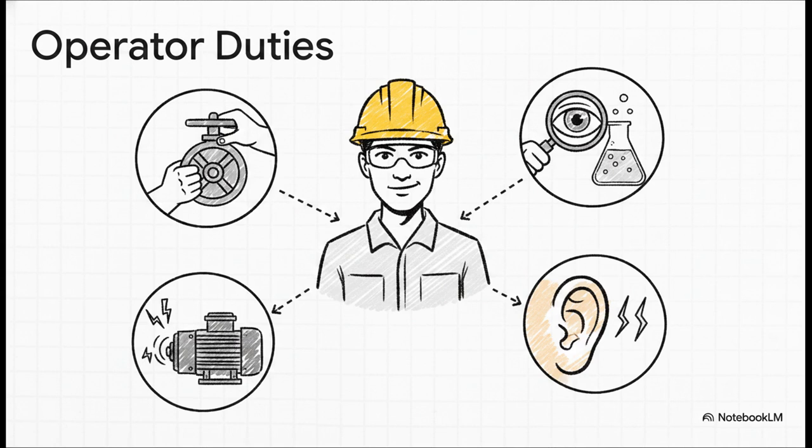You can have all the automated sensors in the world, but it still takes a skilled operator physically walking the plant to ensure safety and keep the ecosystem perfectly balanced. They're out there verifying the valves are lined up correctly. They're pulling product samples, checking pH levels, and looking for cloudiness. They're watching those infrared control screens. And they're literally using their ears and noses to detect a rattling pump or sniff out an overheating motor long before it ever becomes an actual emergency.